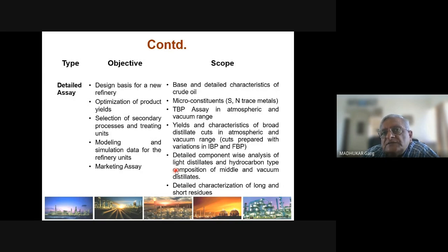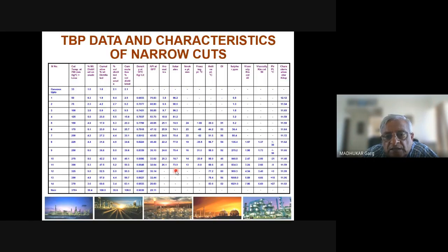But just for now, please remember that there's a technology in the refining industry called catalytic reforming, which produces gasoline and also produces aromatics. So basically, this is one unit which manufactures aromatics, and that is done by dehydrogenation of naphthenes to aromatics, and hence it becomes very important for us that this characterization of the feedstock is done completely.